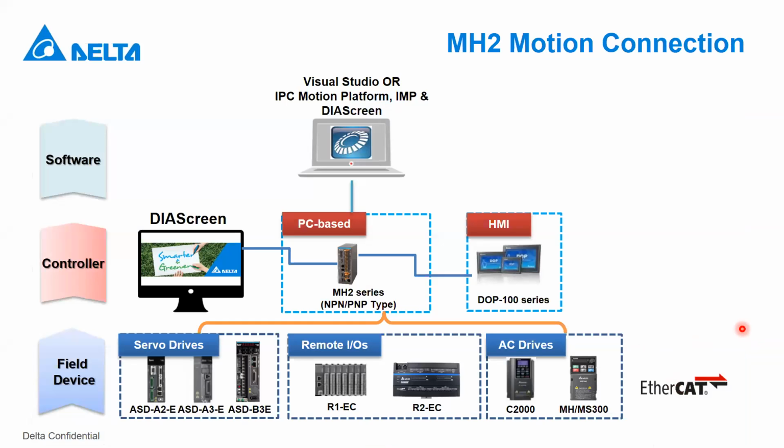And this page will show you what we just mentioned for the MH2. So we can use either Visual Studio or IMP. And you can see for this PC-based controller, we can use either a screen or monitor, or use a Delta HMI. And come to the slave device, we have a servo drive, remote I/O, and VFD.